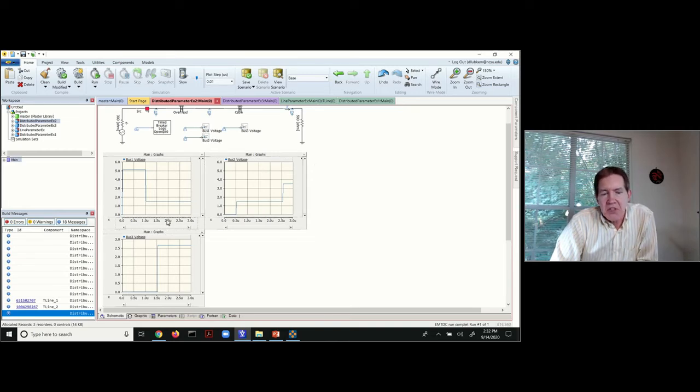And you can see that this is going to be comparable with what we got doing the by-hand analysis. So if you're looking at what's going on at bus number 3, basically you have the time delay it takes for the surge to travel down the overhead and the cable. Then when you look at the reflection coefficient at the end of the cable, you can figure out what this first peak's going to be, and you could also get into more detail about what's happening at the middle point in the circuit as well.